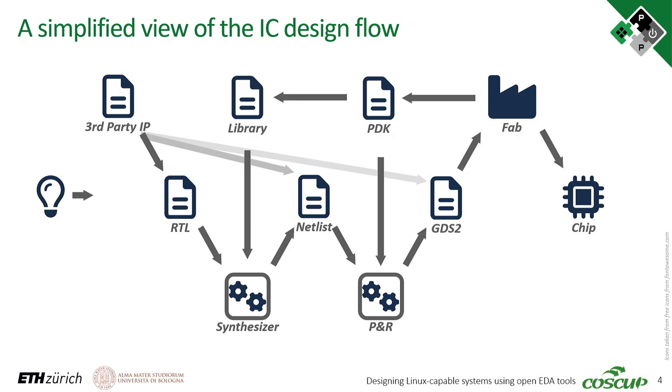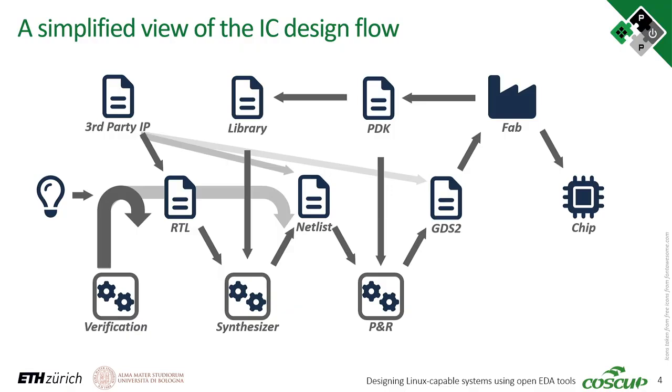And then you quite often also have third-party IPs, so you don't want to design everything yourself because that's annoying, so you go to someone else, like for example Open Hardware Group, and you take some of their designs and integrate it into your design. And obviously, very important, at each step you need to make sure that what you want is actually what you get. And this is done with verification, so simulation, logic equivalence checking, and so on.